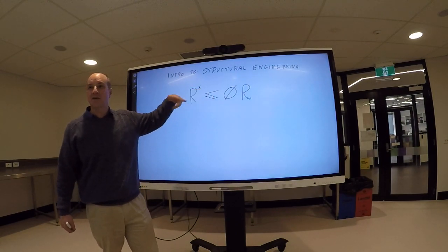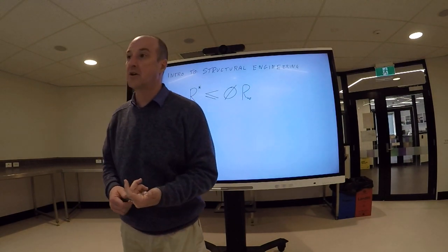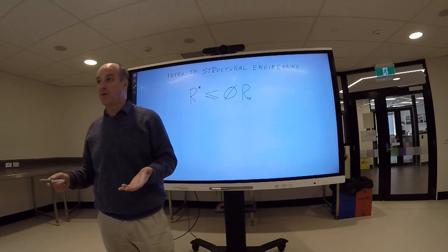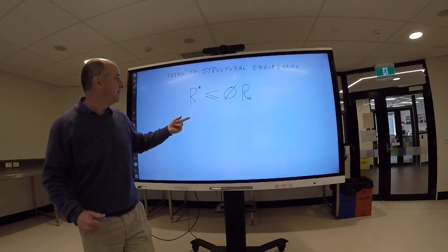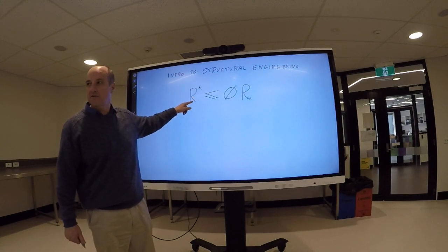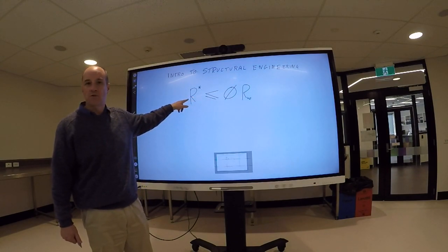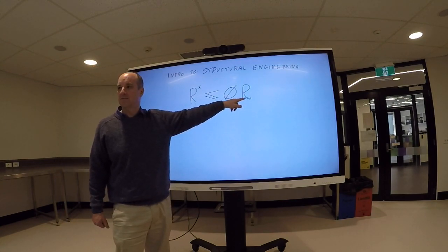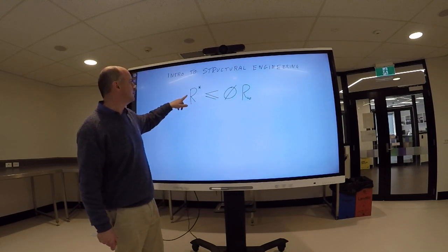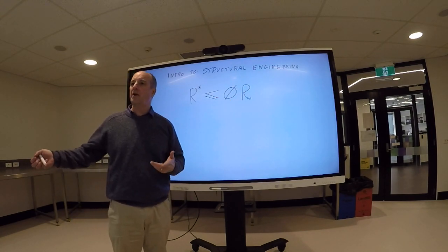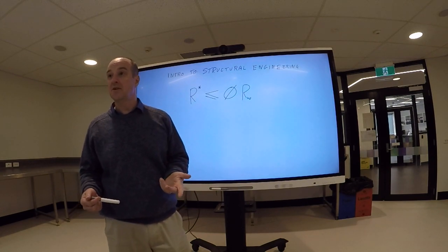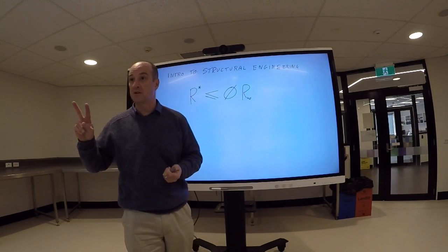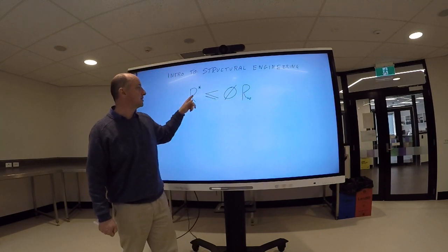The asterisk means ultimate force or ultimate action, okay? We talk about actions, we talk about ultimate actions. It's not just a throwaway word. What it means is that we exaggerate the force or the action and we underestimate the capacity, okay? You might have heard the term factor of safety, okay? If you build something that's twice as strong as it needs to be, it's got a safety factor of 2, okay? That means the capacity is twice as much as the force.